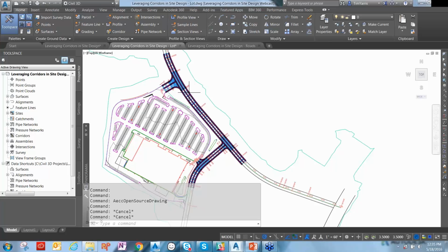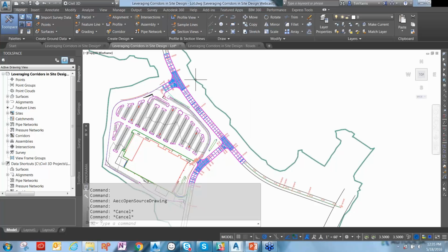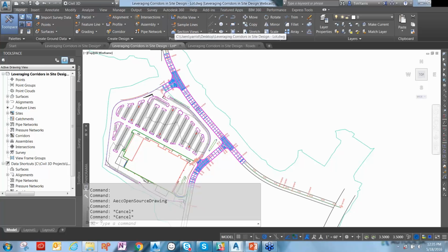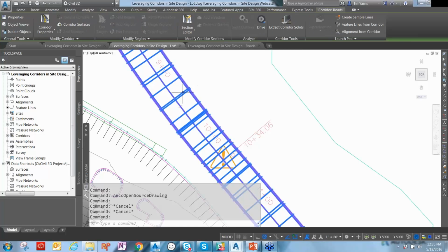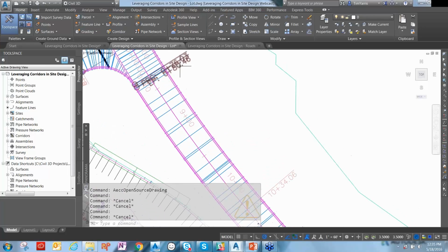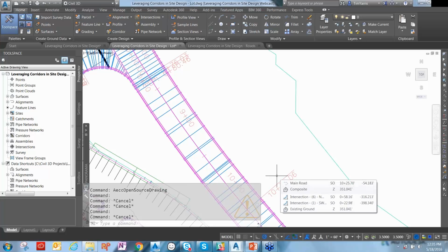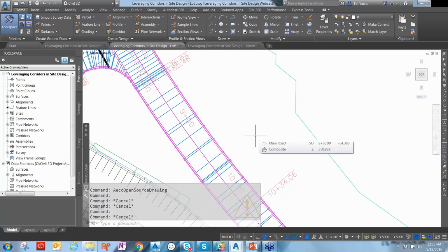If I had this corridor model targeting this surface, and I create a deref to the corridor model, you won't have to bring in the deref to this surface as well. Really all that's going to happen when you bring in the corridor model as a deref, let's see, this is ref, yes, okay. Basically, it's going to recreate the feature line for the daylight, and it's really only going to create geometry of that feature line. It's not going to actually bring that surface in as a target. It's just going to bring it in as a kind of wireframe.